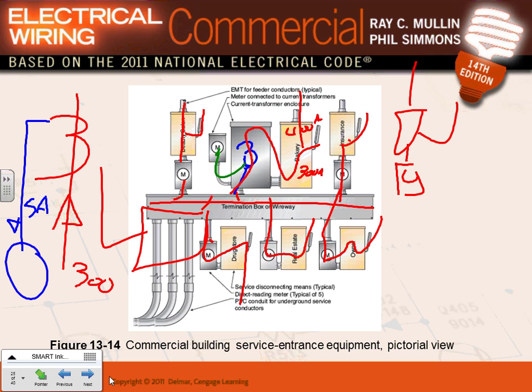That's what a CT cabinet does. Take a 300, they call it 300 to 5. So every 300 amps will be seen as 5 amps. Can I have a thumbs up, Chad? Okay, now half of this will be what? 150. What do you guys think? If it's 150 going through, what do you think this will be? 2.5. Does that make sense? Ratio.